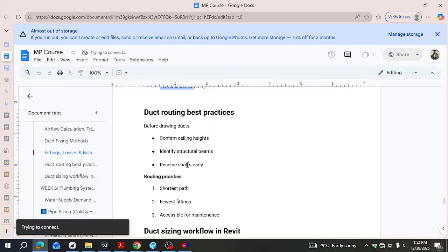So you will not just want to see ducts just on the wall in a building, right? Or within an interior space. So there's usually a duct that's built around it. Sorry, a shaft for that duct to travel there, especially when it's going from floor to floor. That's when you don't have a choice. Most times, if it's a one-story building, you just have to design it. You place your equipment in the roof or in the ceiling or on the roof, and then you pass your duct down into the building and then enter the ceiling and it spreads out. That's the distribution where it takes place, right?